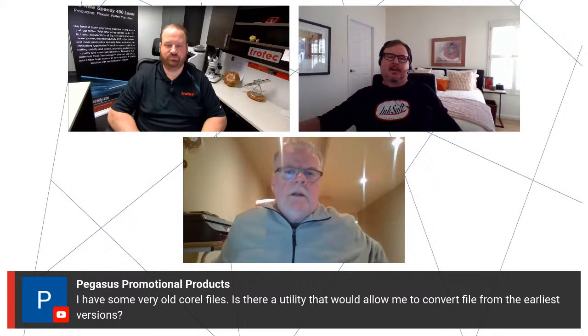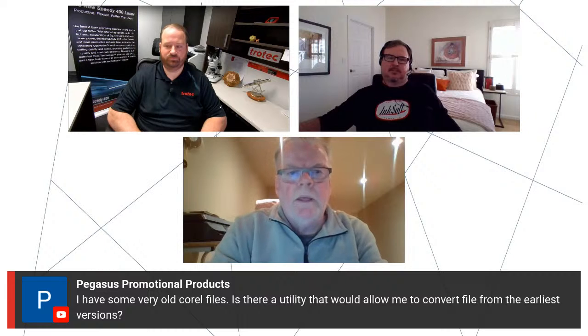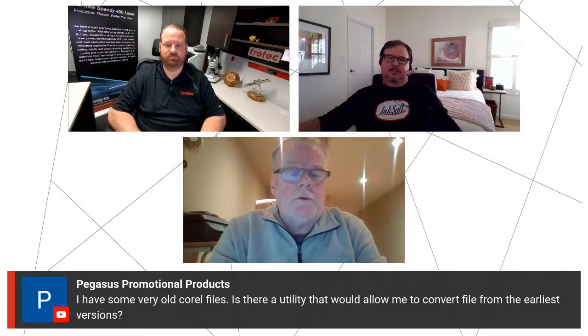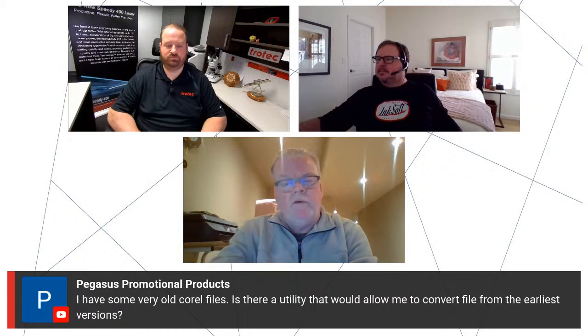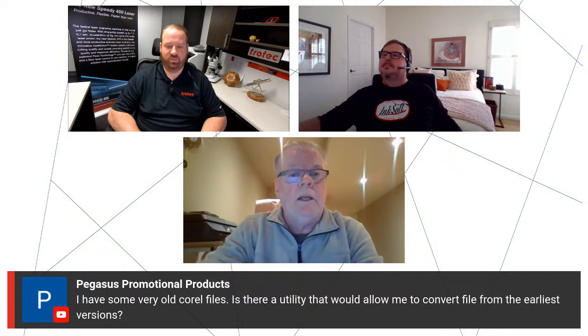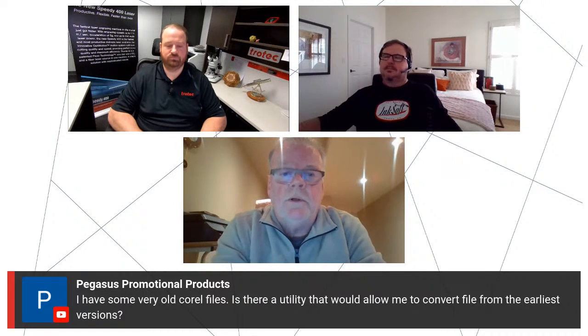Macros, if you go to run macros, you can find it in there. Macros run, and it's called File Converter. That will allow you to convert it to a CDR and set what version you want, or if you took it back as a CMX. Now, a CMX is Presentation Exchange, basically an uncompressed CDR file format. It doesn't have page information, but it'll certainly get all the information out. You can try that as well.